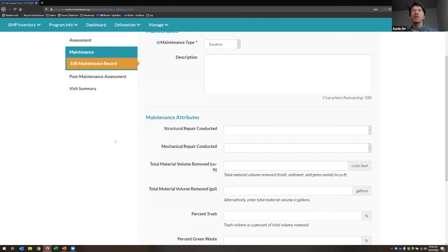The reason we key on design drawdown time and BMP volume is those are two things that the client registering a BMP in their system might know about that BMP. They'll know how it was designed to function. They'll know the volume of it, the shape of it, and some design drawdown time. Or then maybe they know an underlying infiltration rate.